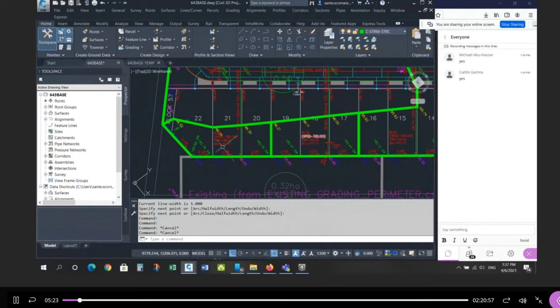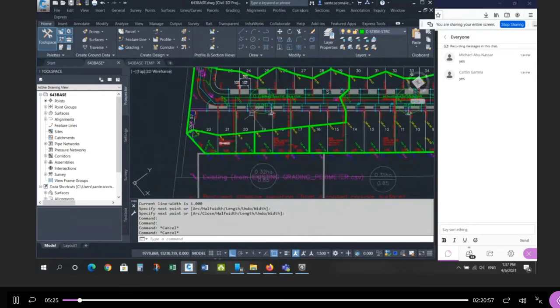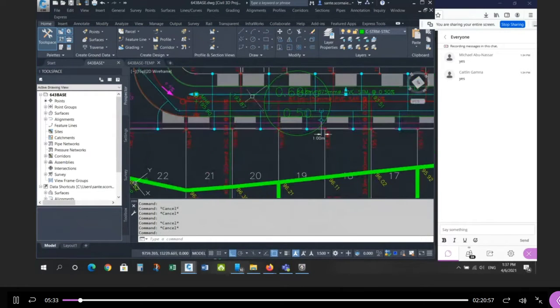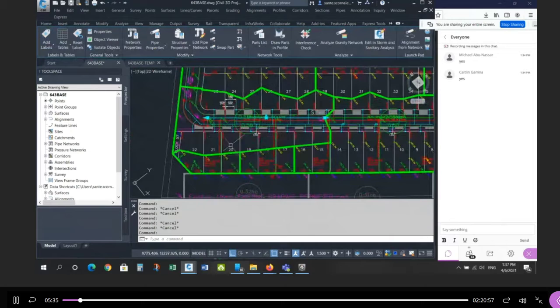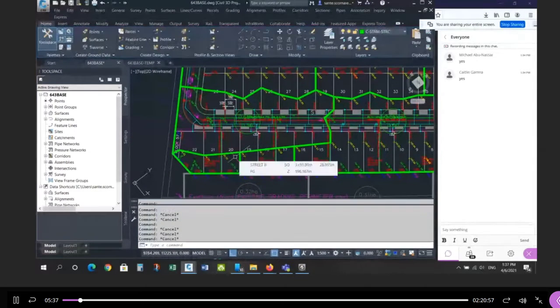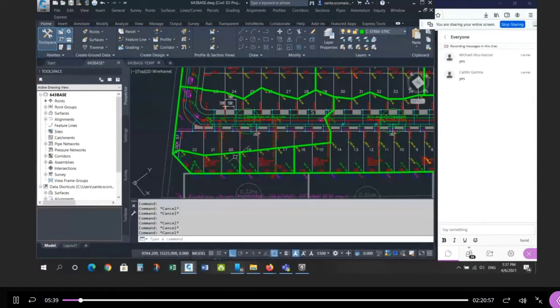So I took the area for this one and the area for this one, and I combined it to the area for the pipe on the street, because eventually these two backyard areas will combine to generate the flow expected in this pipe. Okay, so it's easier if you draw each individual area first and then add them together than to try and combine them. Now if you can combine them directly, all the power to you. My brain doesn't work that way, so I always draw them separately.